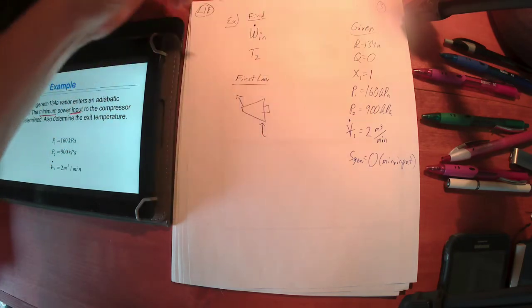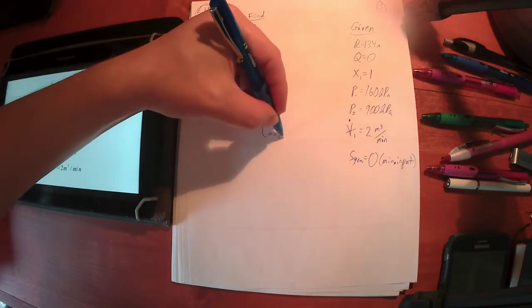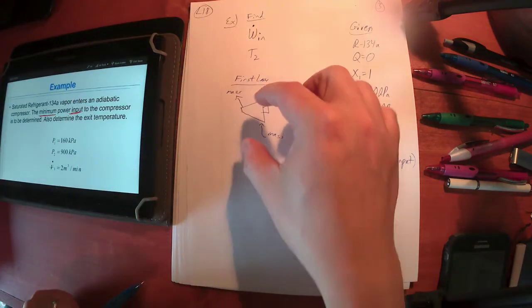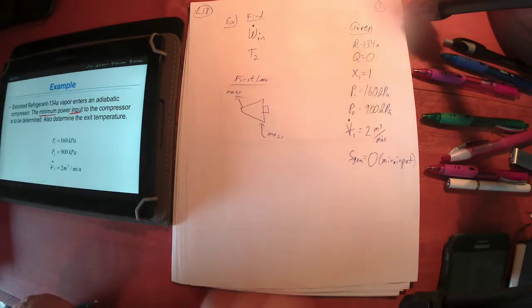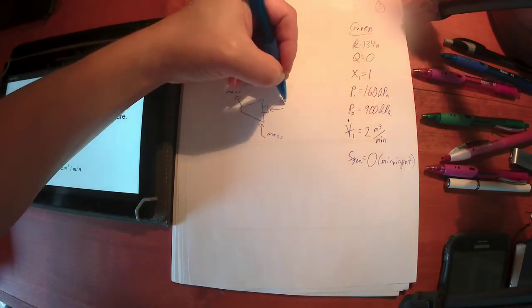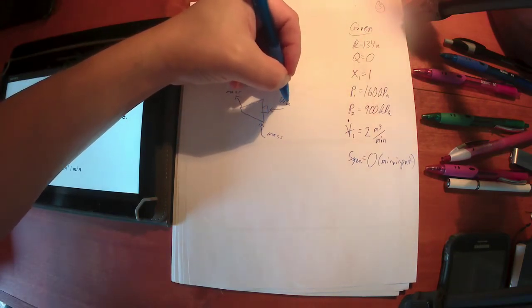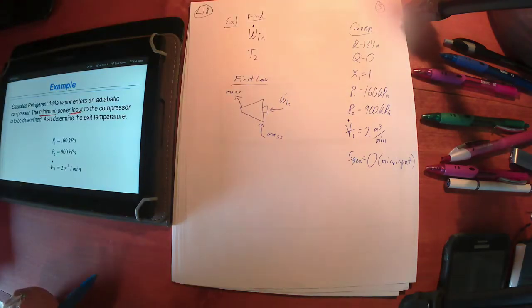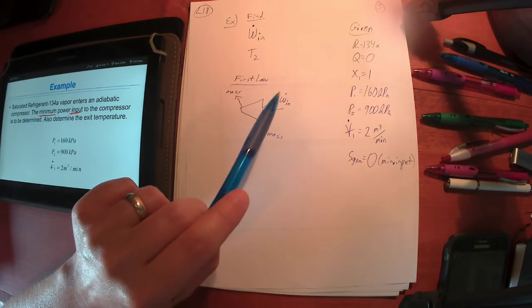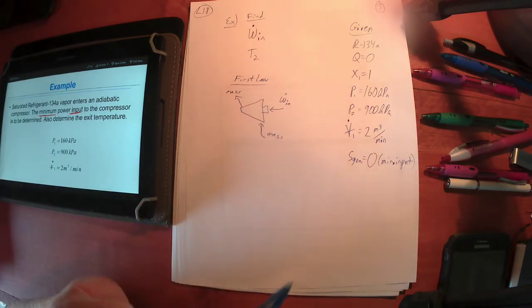So what's crossing the boundary? Well, a compressor always has mass crossing the boundary. The compressor squeezes it down, okay, and it does that by putting in what? A power input. So the basic compressor has these three energy quantities. We should know that from chapter 5, okay. Power in, mass in, mass out.